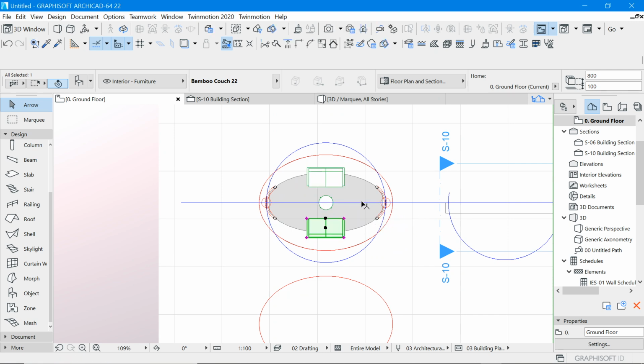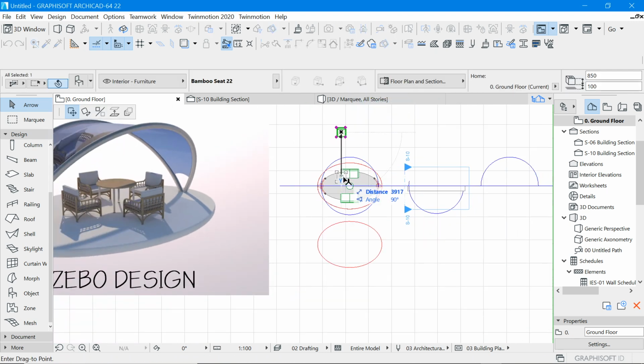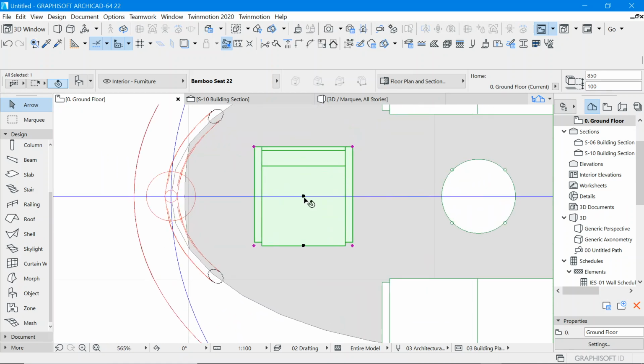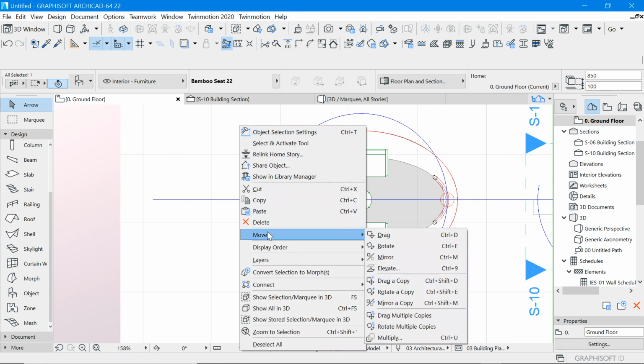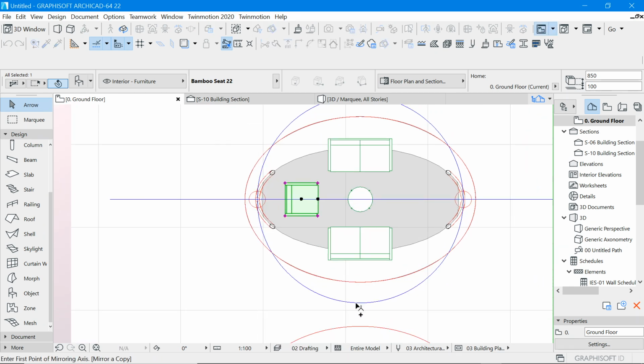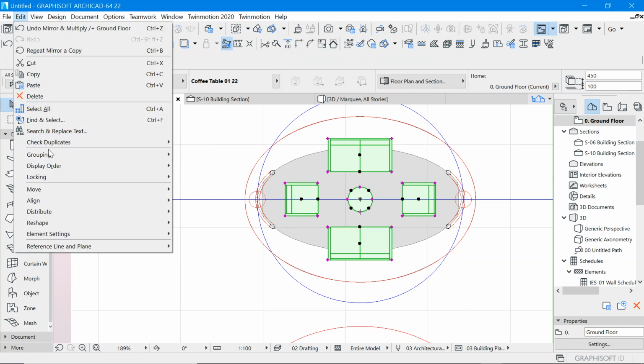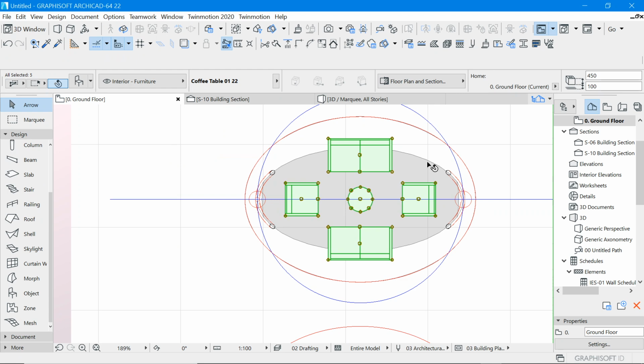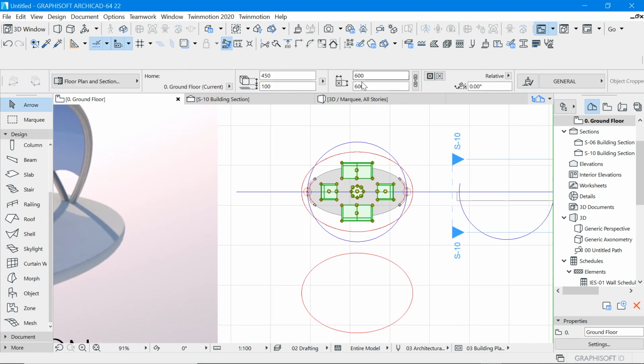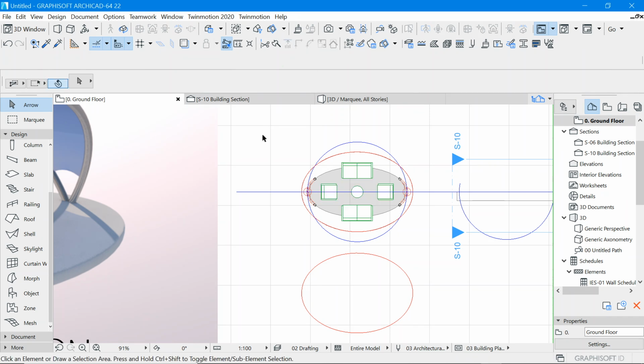and then we get closer, then we add another one somewhere here, but rotate it. And then also make a couple of that for symmetry purposes. Then we can group all these together. Group. And now if you go to their settings, you notice that they are 100 millimeters off ground. So you put 0 here for them to come to ground.